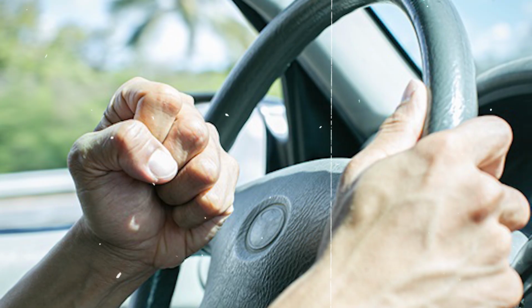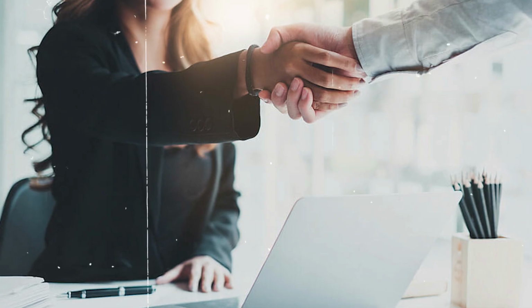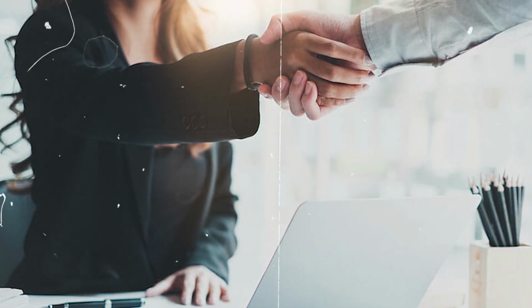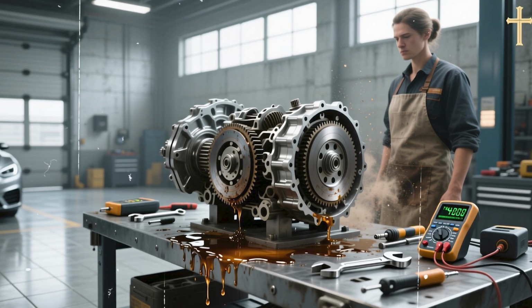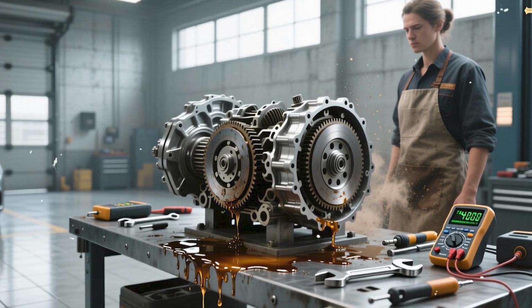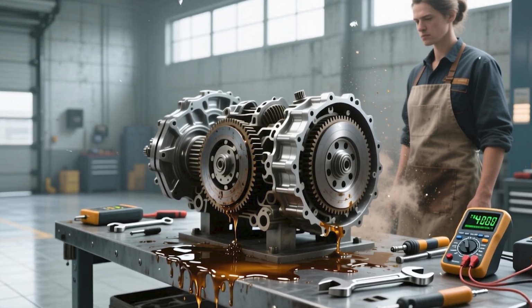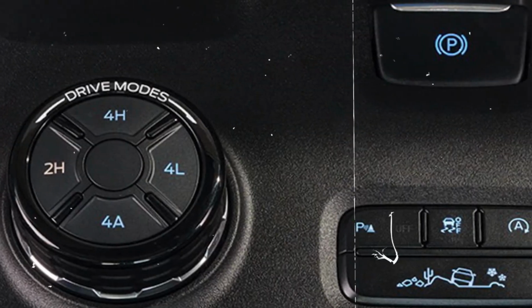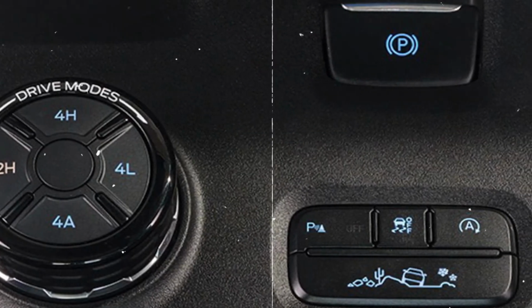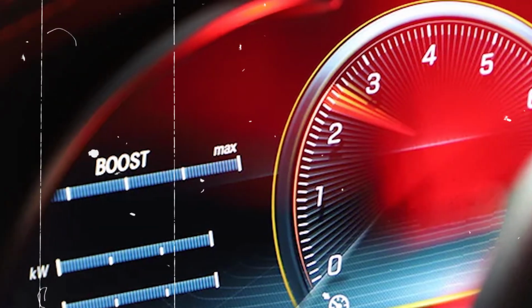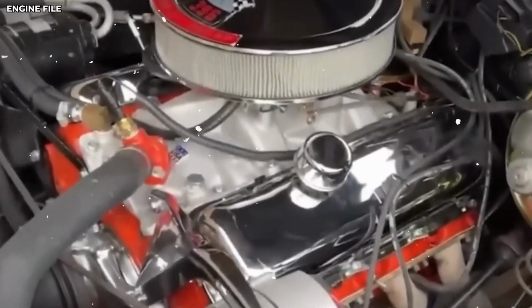In practice, this rarely happens. Dealerships would need to prove the reset directly caused the failure, which is nearly impossible since you're not changing calibration, just clearing learned data. But the legal risk exists, especially if you use Forscan to make permanent modifications. Understand what you're agreeing to. Second, you absolutely must drive aggressively immediately after any reset procedure.